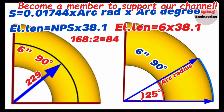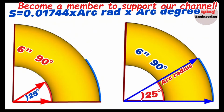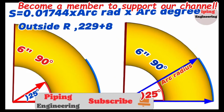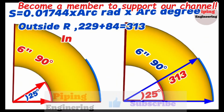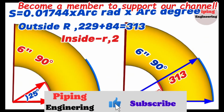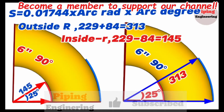If we subtract 84 mm from 229, the number obtained will be the radius of the inner red color arc of the 6-inch elbow. So, outside radius of the 6-inch 90-degree elbow, 229 plus 84, equals 313 mm. Also, inside radius, 229 minus 84, equals 145 mm.